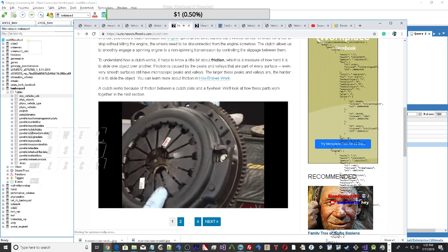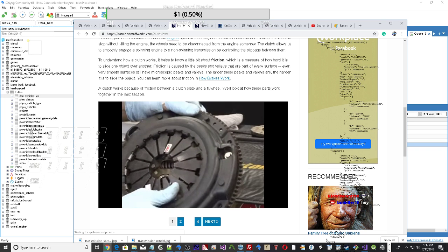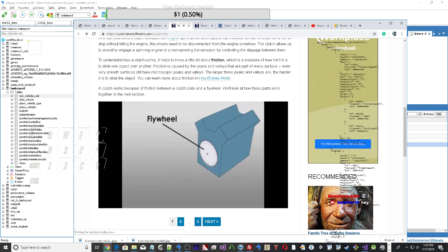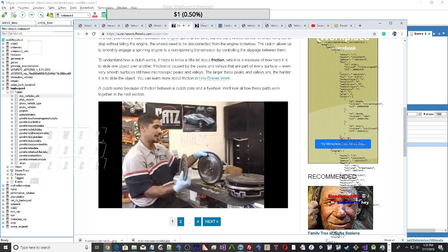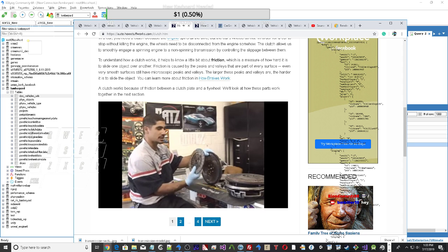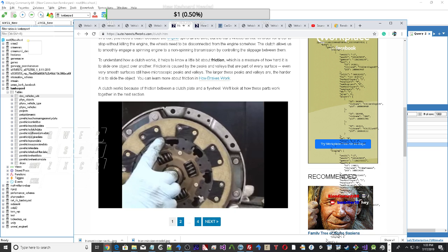wheels[PxVehicleDrive4WWheelOrder::eFRONT_LEFT].mMaxSteer = PxPi * 0.3333f; wheels[PxVehicleDrive4WWheelOrder::eFRONT_RIGHT].mMaxSteer = PxPi * 0.3333f. Set up the tires.